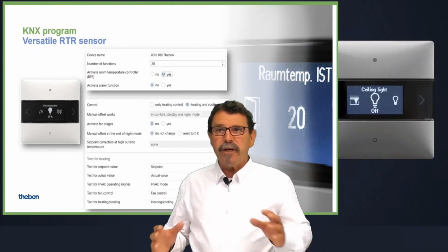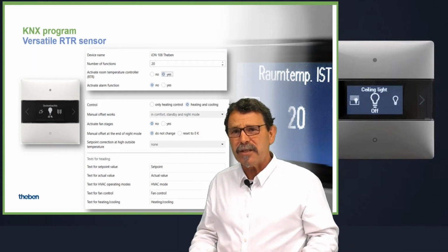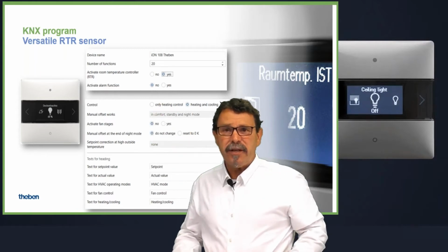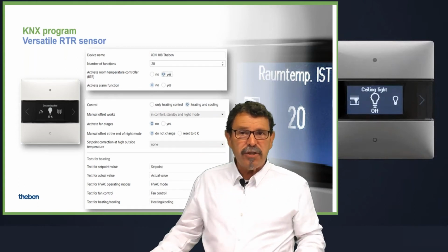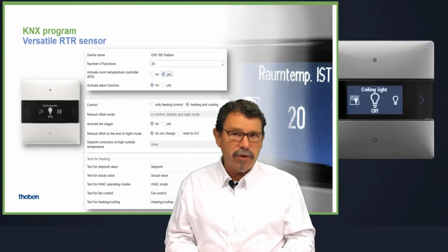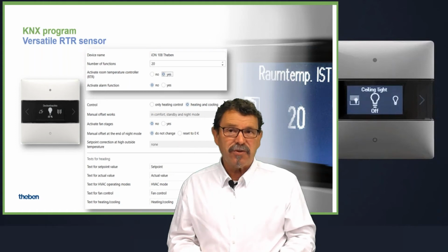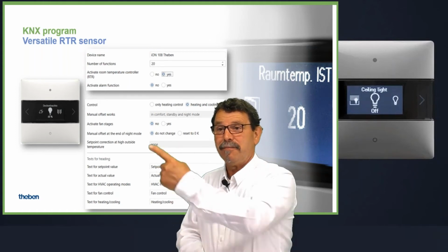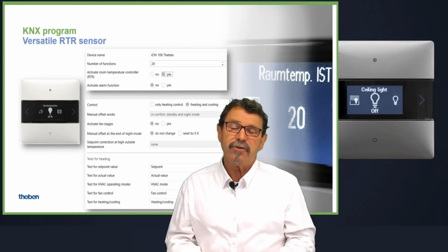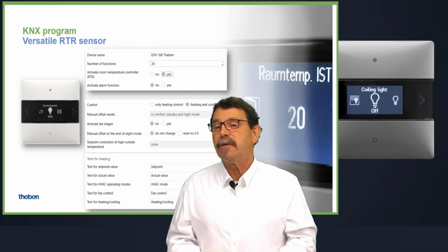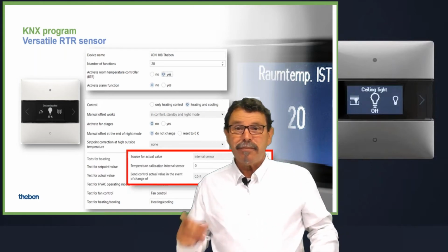The application, when we focus first of all on the room temperature control, so the temperature control in its own, you see here we do have here the option just heating control, or if in most of the cases we need this application, heating and cooling. So it depends on which zone of the world you are located, you definitely need the cooling. This controller is supporting that. Plus, you discover probably here fan stages, so we can do the airing, fan coil control, for instance, or air recoveries. However, the controller supports all these functions. Yeah, it's up to you, your choice.